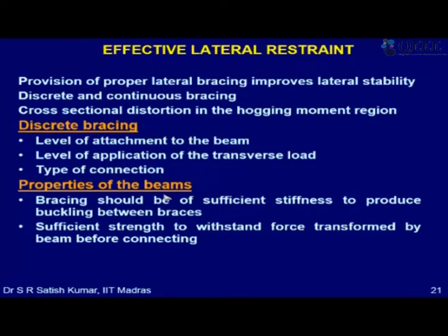So that is basically about lateral buckling of the beam. Now I would try and avoid lateral buckling if possible in many beams. So how do I do that? Let's say you can provide what is called discrete bracing.